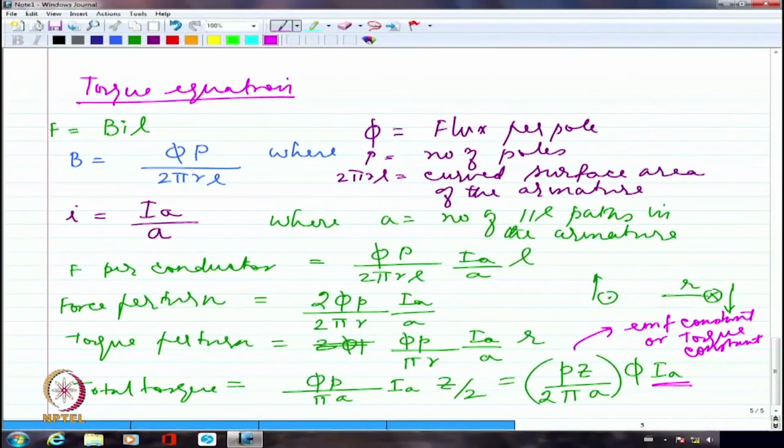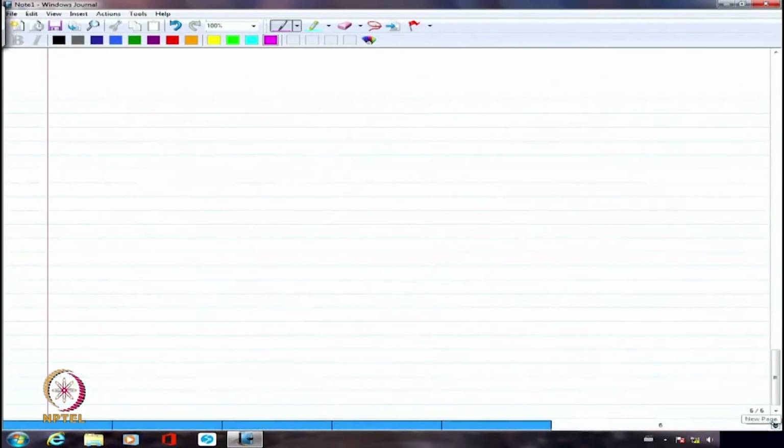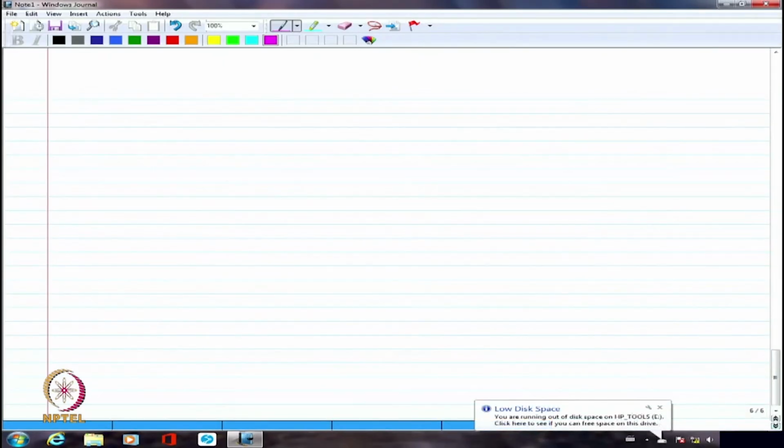The armature resistance or the field resistance, if you want to get those, are generally measured. Either we do a VI test, that is, we apply a voltage, pass a current, and say V by I is R, or we use a multimeter, depending upon how accurate your multimeter is or what kind of accuracy you require in your test. Generally the nameplate details will contain all this data at rated excitation and rated speed. The voltage and current will be specified for that, and the torque also.